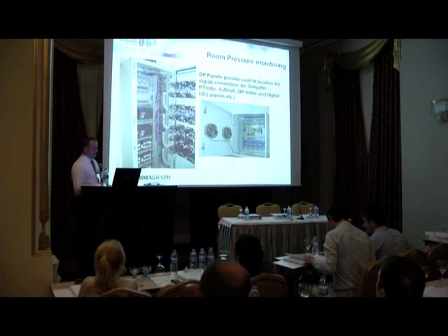You could decide that actually I want to look at all 5 micron particle counts only. So you just select 5 micron particle counts. That will tell you how many there were in the last month. Or you might just want to look at all temperature humidity sensors in the last month. It gives you the ability to pick and select what alarms you want to look at. Generally, you'll probably want to look at all alarms for the system, and then if there are any deviations, you can write reports, etc. as to why.